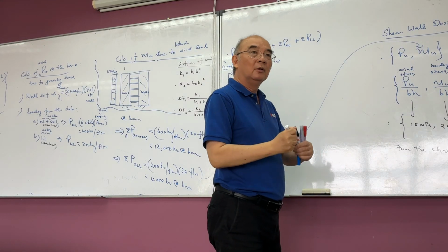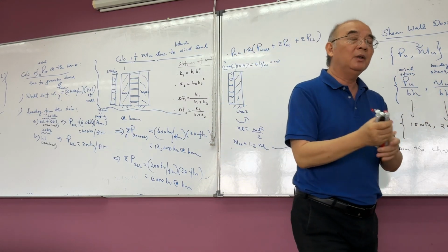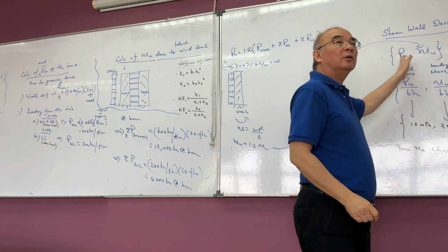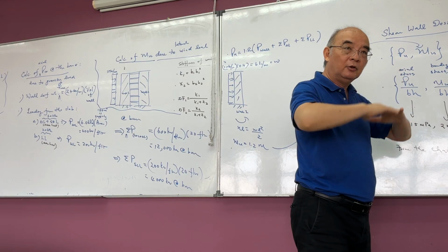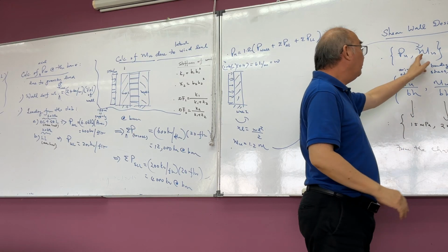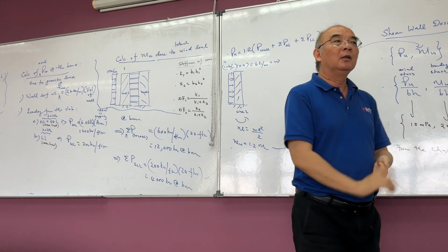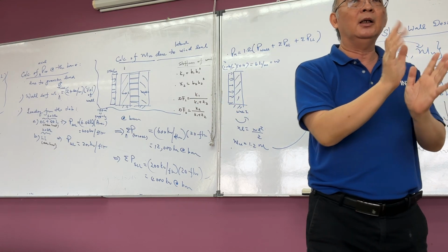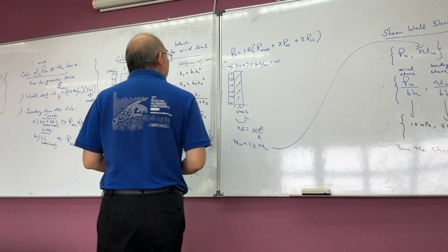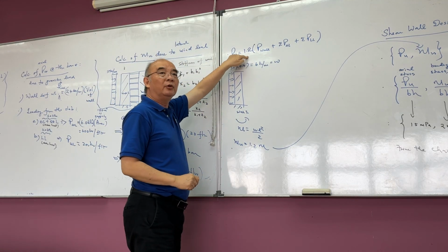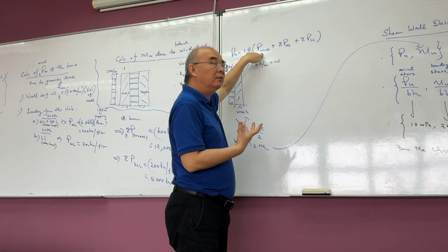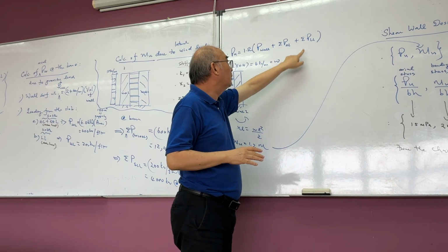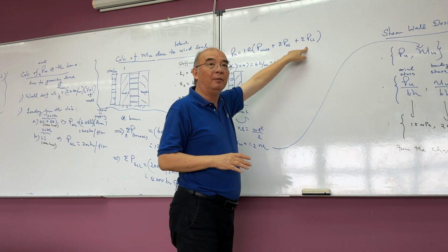Okay? Alright. So let me summarize. This one PU is coming from the gravity load. MU is coming from the wind load. Now gravity load, I think is easier for you to calculate, right? So the gravity load, PU, is 1.2 coming from the wall itself, the loading from the slab, and also live load from the slab.